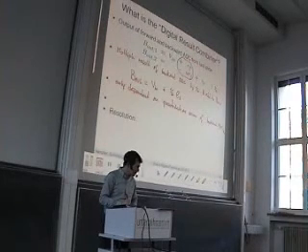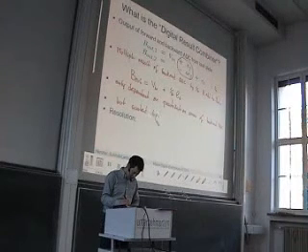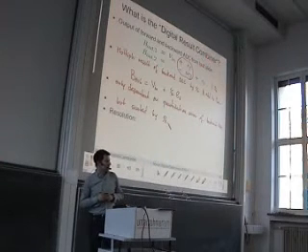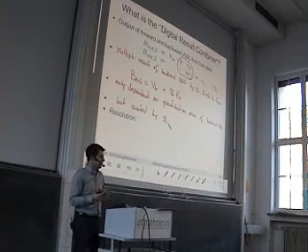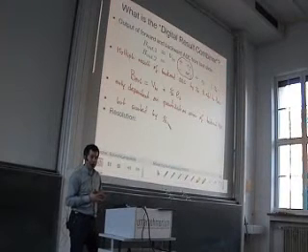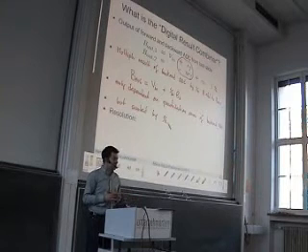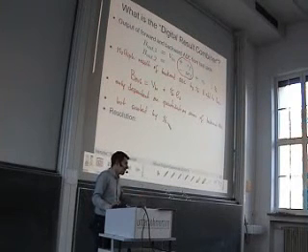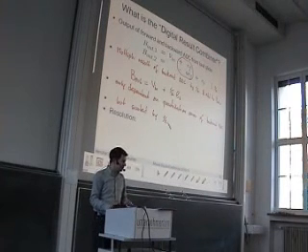And the second important point is this quantization error is scaled by 1 over A. And this is the advantage of this technique. You might say, okay, there is still a quantization error of the backend ADC. Yes, this is right, but we scale this by a factor of 1 over A, so the quantization error of the fine ADC is reduced by this gain in the first stage. And this leads us to the resolution that we can achieve.